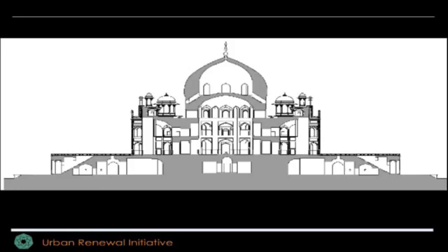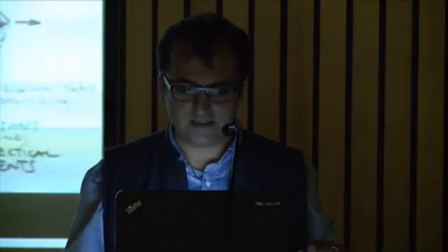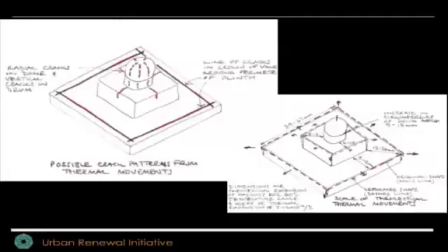As a result, today, when a building this large is built, engineers introduce what is called an expansion joint. What is an expansion joint? Literally, there is a gap between two columns and so on, so that when the building expands, it can do so freely. But Humayun's tomb does not have an expansion joint. As a result, there are various cracks. That is one of our structural engineer Stuart Tappan's drawings, and that is the line of cracks that you see at Humayun's tomb through the plinth.